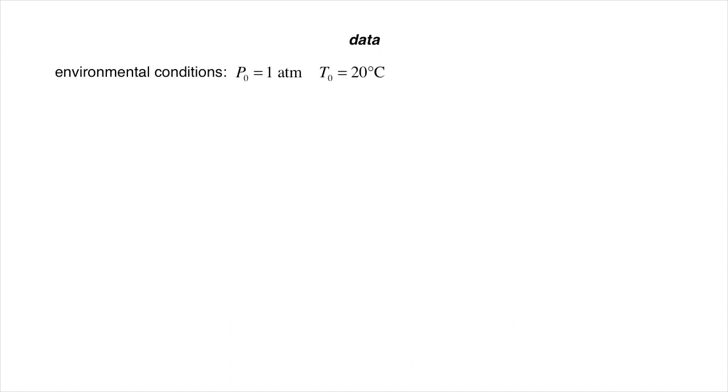In order to perform these balances, we'll need some data. First, we'll need to decide on an environmental temperature for benchmarking the value of heat. In the case of a heat engine, we often pick the cold reservoir temperature Tc, since it's usually implied that any heat rejected to the low temperature reservoir has no additional work generating value.